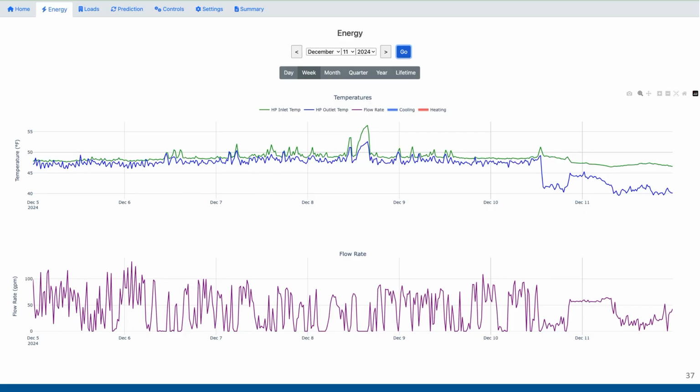Genius. And so these guys would have got killed on their energy bill. Not only are they paying for that electric boiler, right? But same problem. They have a limited capacity in the summertime because they're not drawing down their ground heat exchanger temperature. So what happened here is we saw this, and it stood out right away.